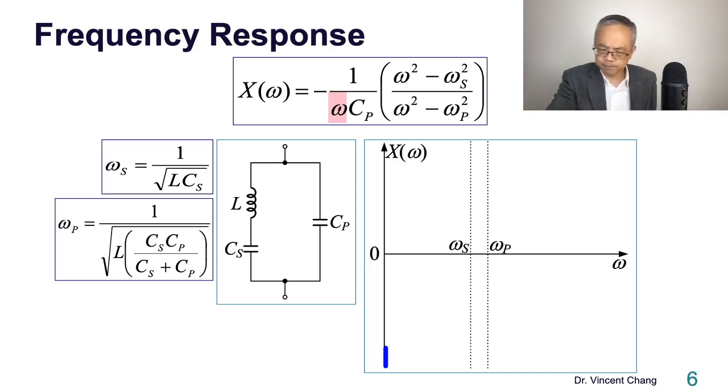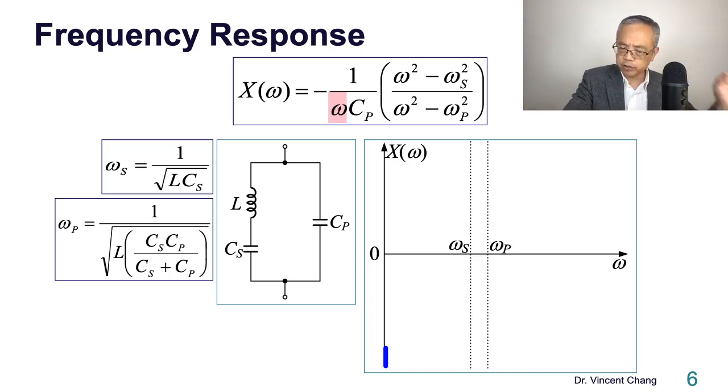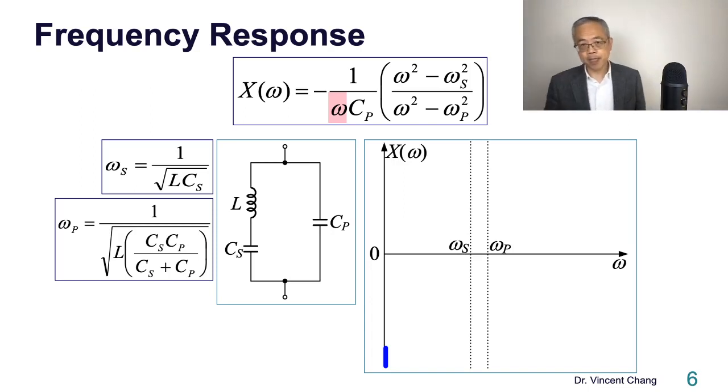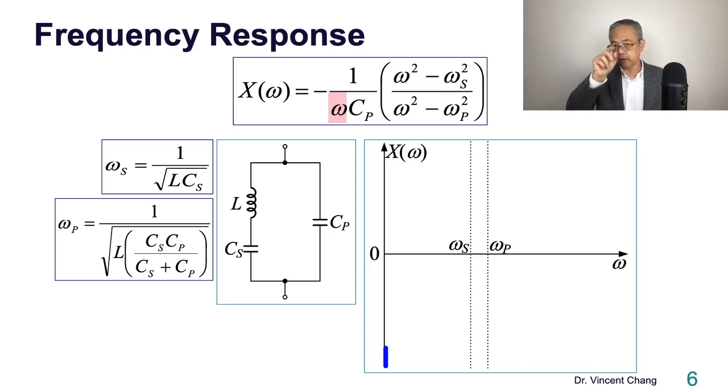This is actually a lesson you were supposed to learn when you were a freshman college student, right? Calculus. So when omega is DC, omega is 0, so the reactance is infinite. But why infinite? Positive or negative? Negative, because the parentheses represent a positive constant. So negative infinity. And then when omega starts to increase, the denominator goes up, so after inverse, the value goes down. But the value going down is a negative value with the negative sign, so it goes up like this.